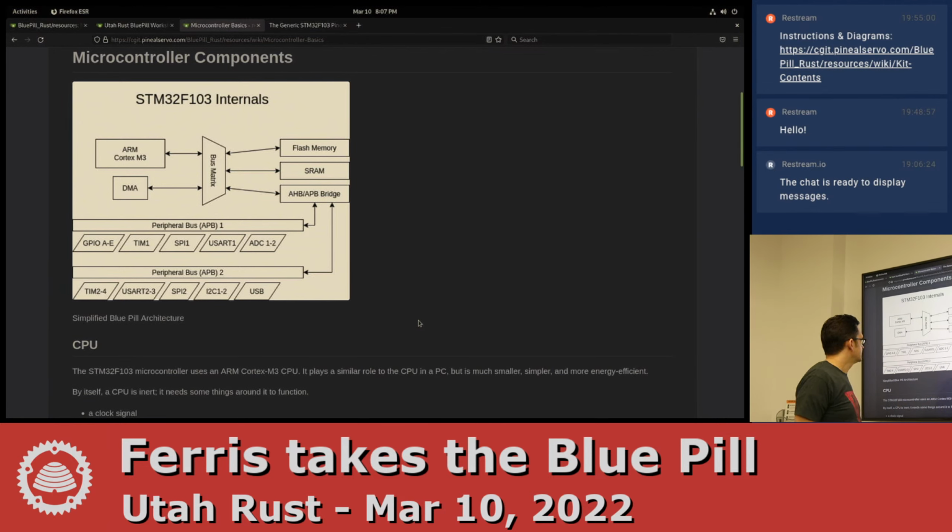These are really handy. They're the analog to digital converters. That means you can hook up any kind of sensor or a joystick or a potentiometer, something that has a continuously variable voltage, and you can read what that voltage is periodically. In fact, you can read it very quickly. I think you can go up to a sampling rate of 15 megahertz or something like that. So there are projects where people build little toy oscilloscopes and things like that.